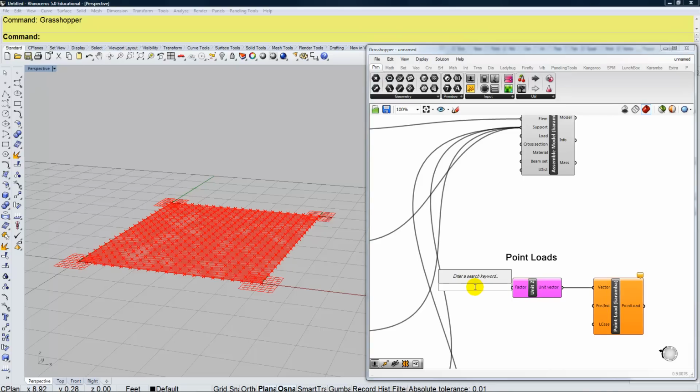I'm gonna make a number slider that is set to 2.000. So with this load I want a lot of decimal places, so I'm going to have 4 decimal places for the load, and I'm going to go ahead and plug that in. So I've set up my load direction, which is positive z, and my load amount, which is 2 kips.